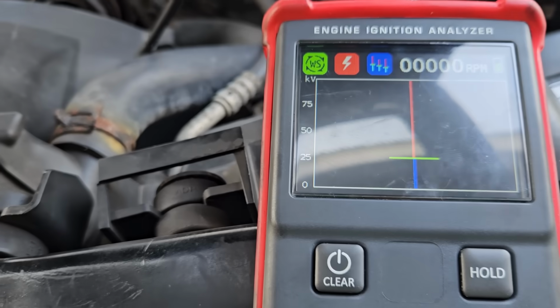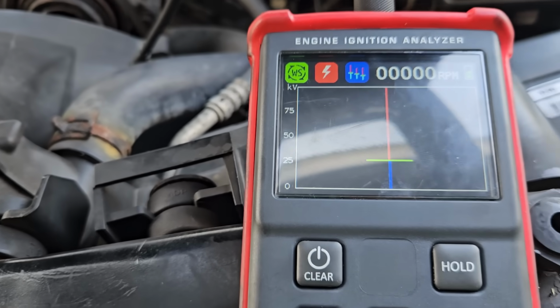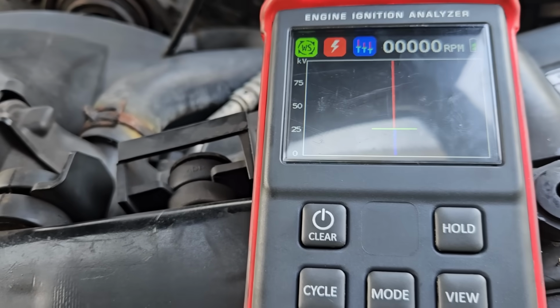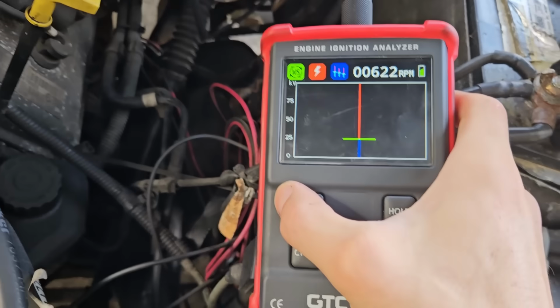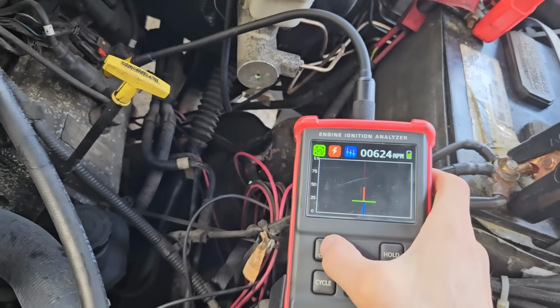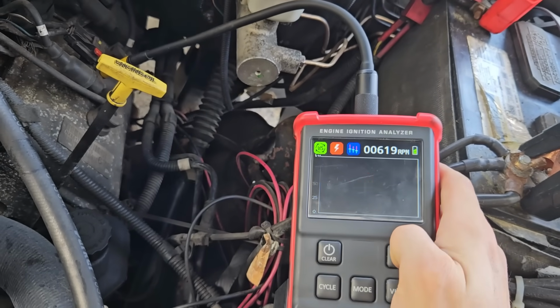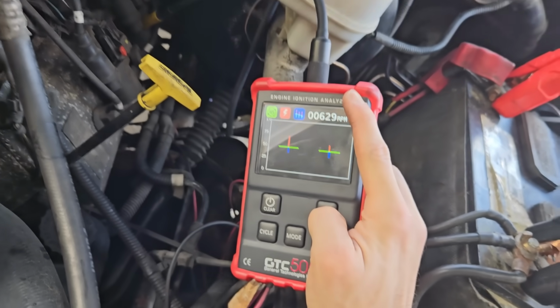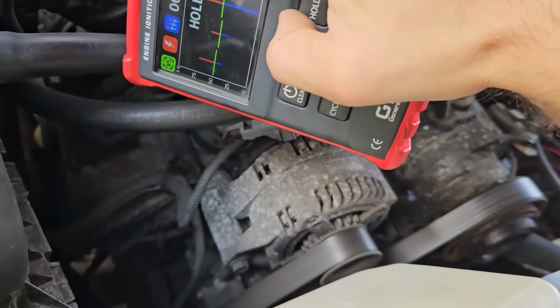Now it's set up to record 16 values. When we press the hold button, it saves the last 16 readings and draws a line at the average. Press hold again, and it starts recording into a new sample. You can build up to 16 samples on one screen, which makes it really easy to see the difference between cylinders. You can even compare the same cylinder under different loads to see how it responds.